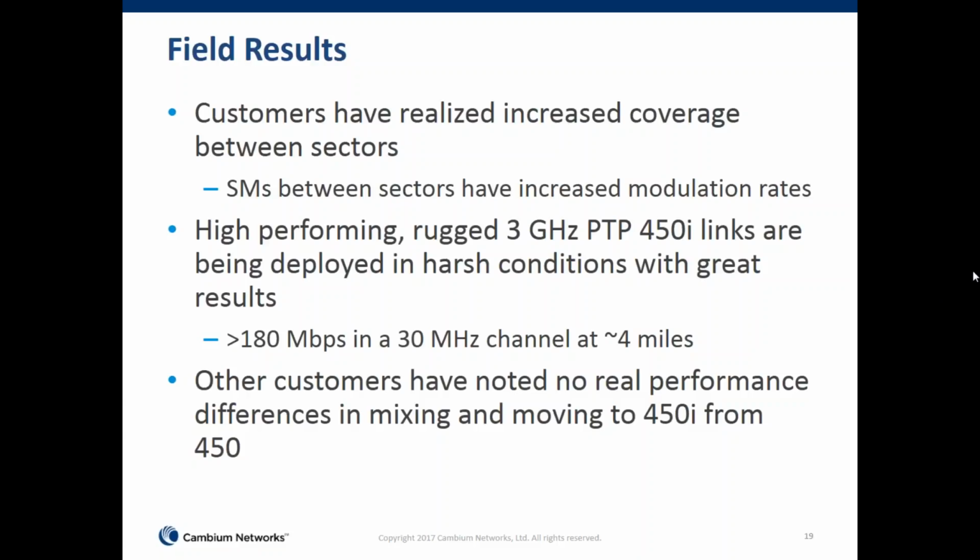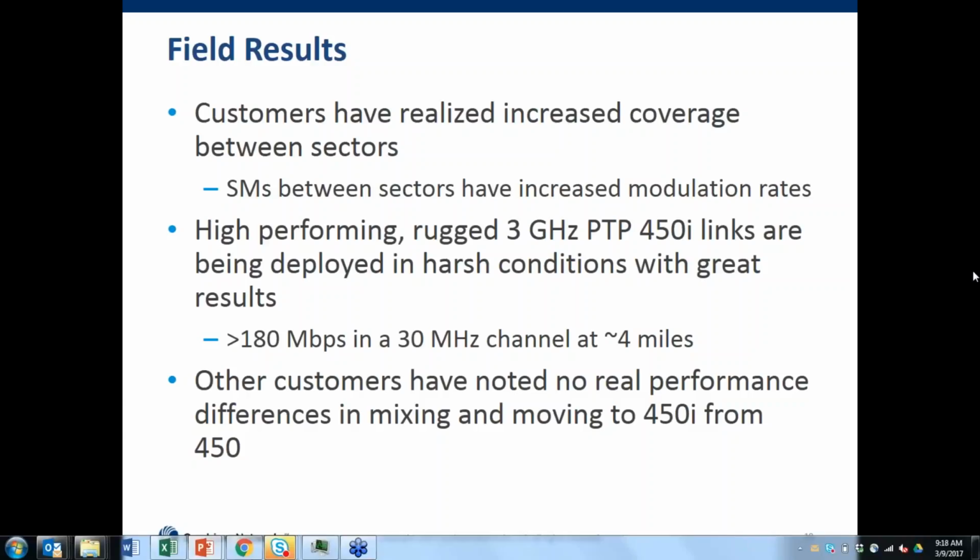So if you have nominal 48, if it's negative 48 DC, that cannot be applied directly to the radio. You need to isolate that power supply. So using the enhanced AC plus DC power supply, you can hook that negative 48 directly to that device, and then the PoE out goes to the radio. So that's why you would need that in that case.